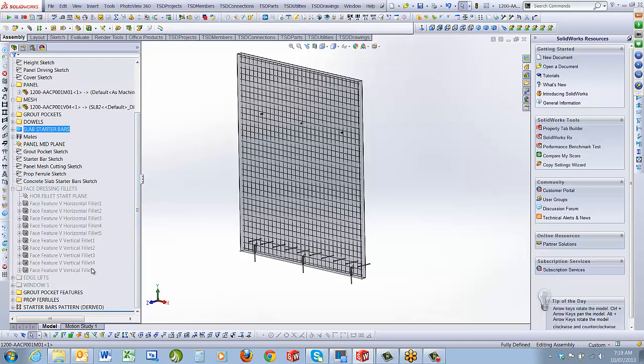They're just simple V's. You can create any shape you like and any cut. Now you also should note that with these, we've actually got an extrusion that if there's a horizontal, the extrusion cannot go all the way across the face. The reason for that is because we have names on our faces, so that when we actually cut the face, we need to keep the face consistent on the panel.